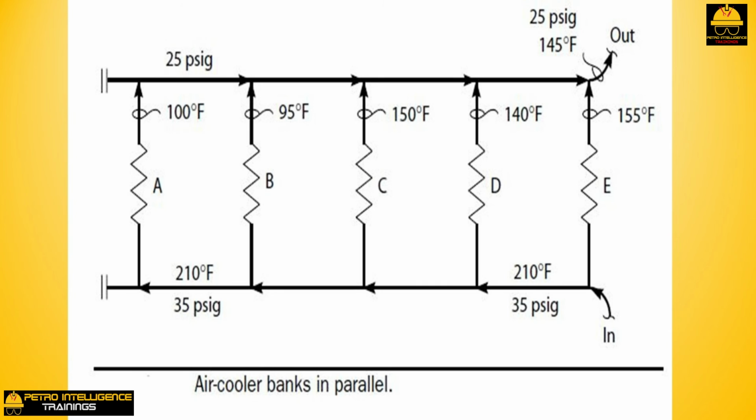The mechanism that causes this often severe flow maldistribution is based on low-temperature dew-point corrosion, as explained below. Here is a rather common example, assuming that the main corrodants are chlorides in a hydrogen sulfide-rich, condensing hydrocarbon vapor. 1. A small amount of ammonia is injected into the overhead vapor line to control the pH of a downstream water draw. 2. Vapor phase ammonium chloride is formed. 3. Tube bundles nearest the inlet header tend to see perhaps 1% more flow than the tube bundles farthest from the inlet header. 4. Bundles seeing the lower flows have slightly lower outlet temperatures.